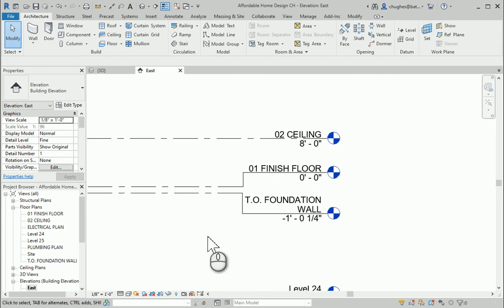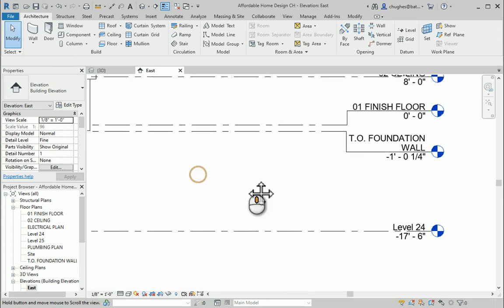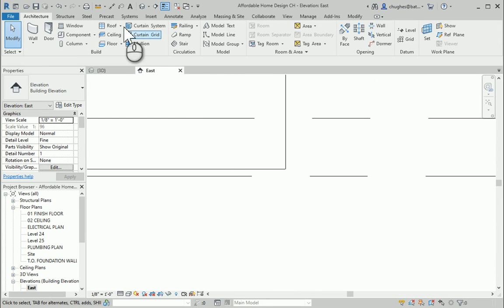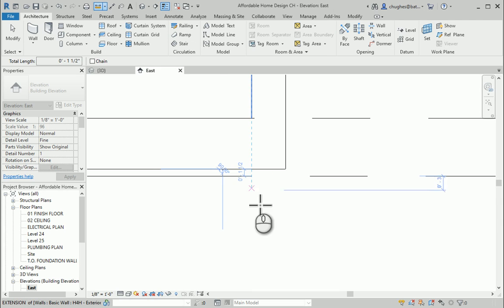There we go. And so there we have that to go through and adjust. Okay. Now here's what I'm going to end up doing: you're going to see that level is set below. So when I take my measure tool and measure from the bottom of the floor to there, you're going to see it says 1.5 inches. So that's going to account for that 2 by 6. So real dimensions, 1.5 inches by 5.5 to set that up.